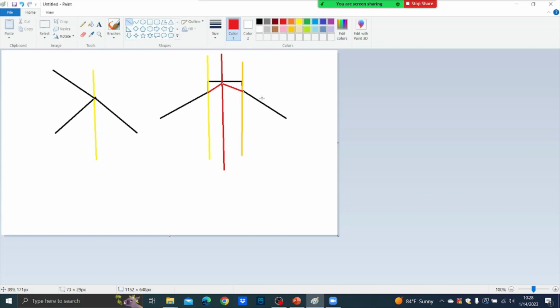Understood? In our roads we have a center median of 1.5 meters, so that is a narrow median. If we are going to have, say, a 3 meter median, then of course your axis of rotation is like this. If it is lesser, a narrow median, your axis of rotation is the center line itself.